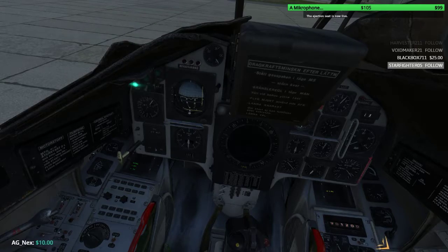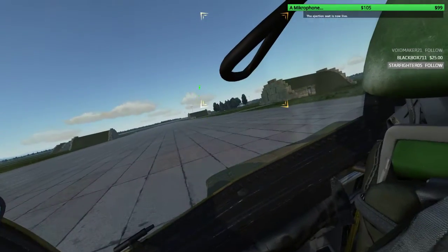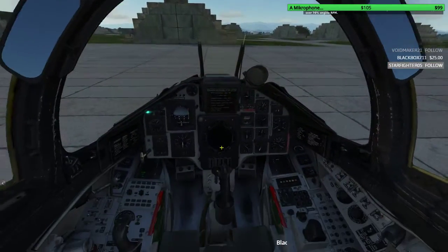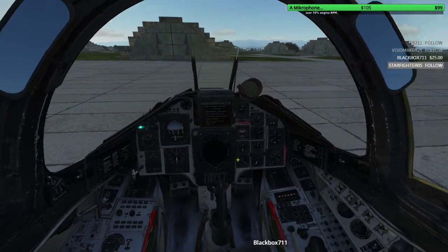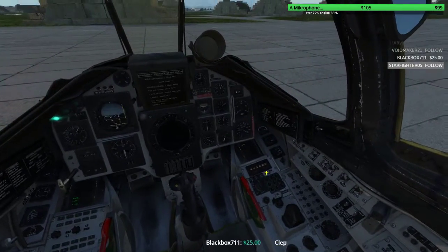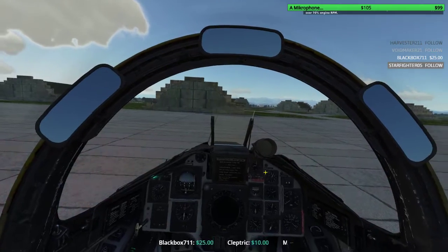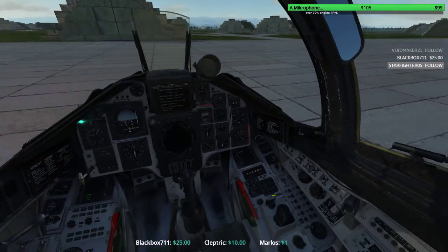Set the ejection seat safety to off by turning the ejection safety lever above and behind your head to confirm that no warnings, except the green landing gear lights, are lit on the warning panels. One exception is for the external tank fuel warning, which will disappear over 70% engine RPM.